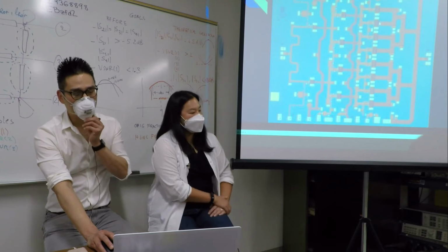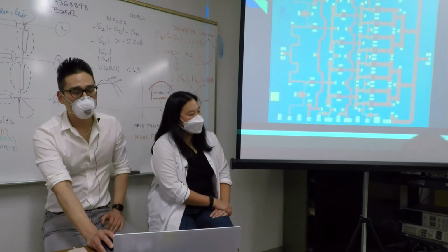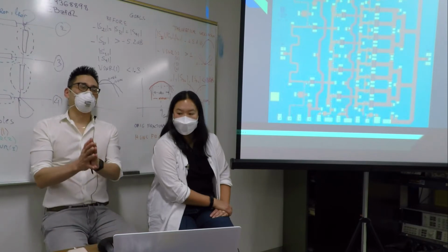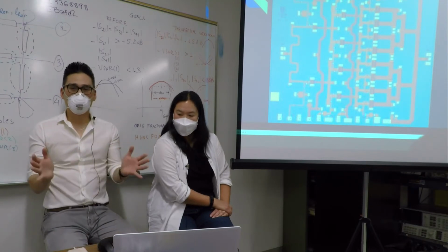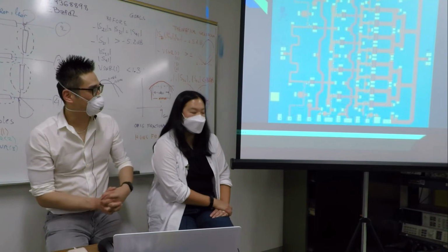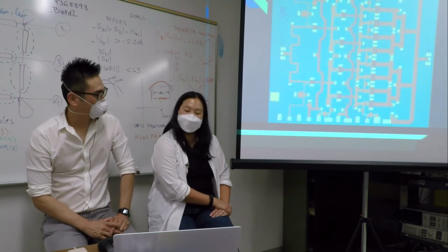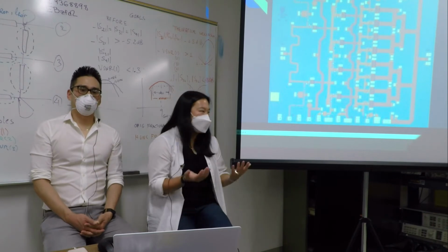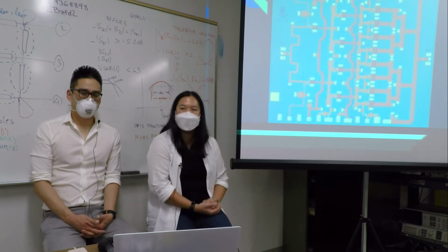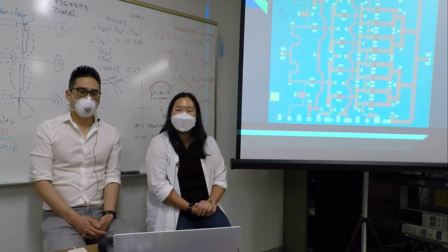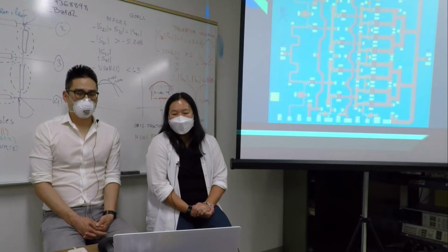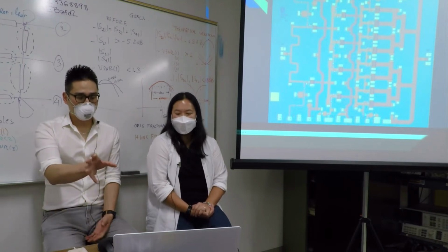And so in order to keep up with the technology advancing, one must create more and more advanced models, so that the designer can then use something that's relatively predictable. And then, obviously, as you work, you will gain experience and knowledge, and you're like, okay, if I'm seeing this kind of response on the screen, I probably want to move somewhere else on this Smith chart.